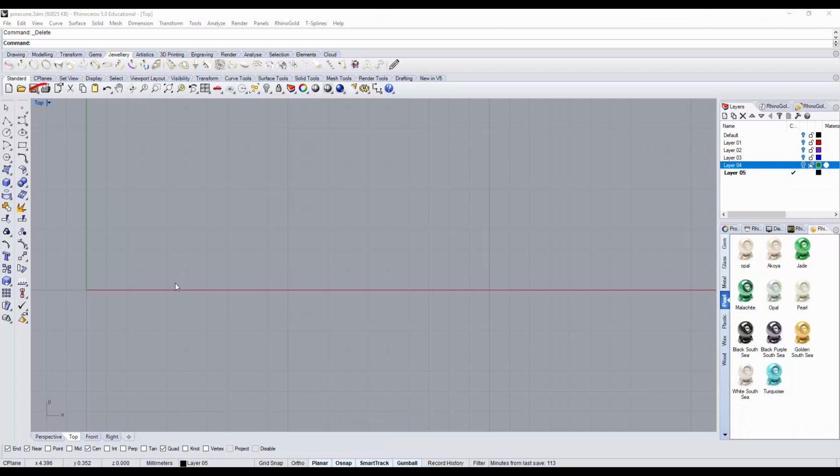Let's start from the top view. So we're going to use the curve tool and try to draw the first element there. What I try to do is create some sort of triangle-ish shape, and you can also use the control points. You can turn on the control points and edit until you feel the form fits what you want. After that, I'll just simply mirror it to the other side. If you like a really organic look, it doesn't have to be symmetrical.